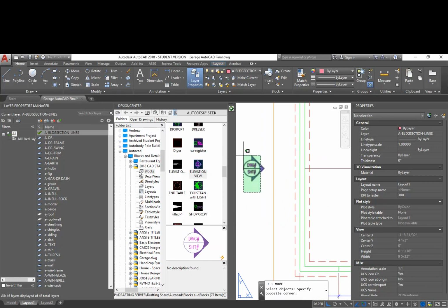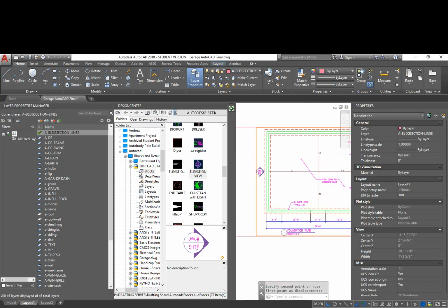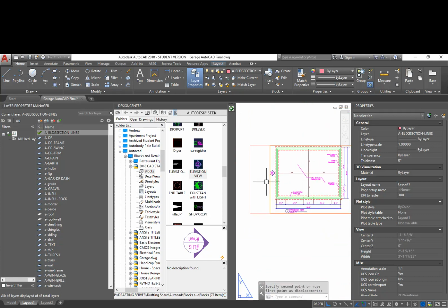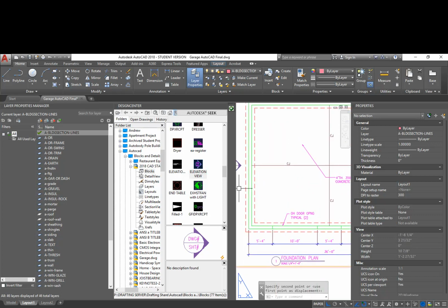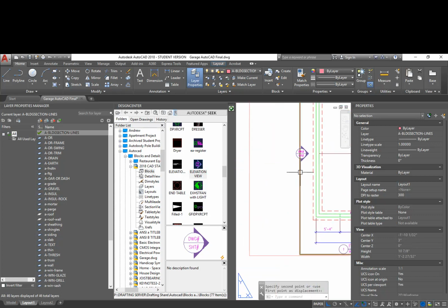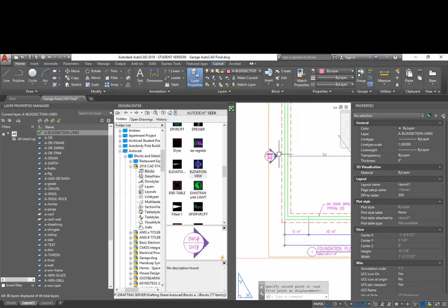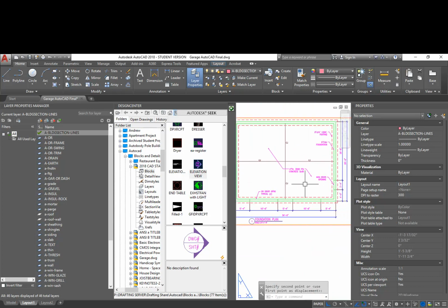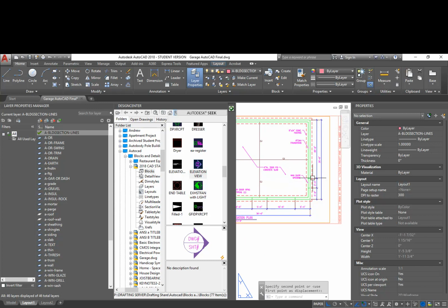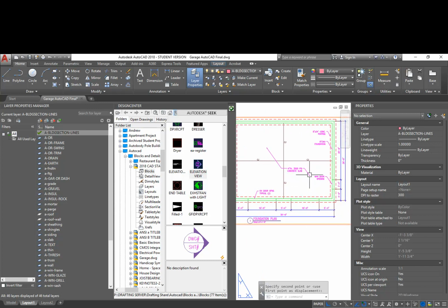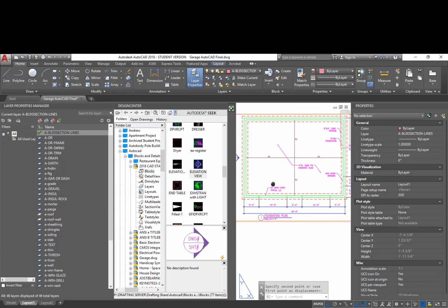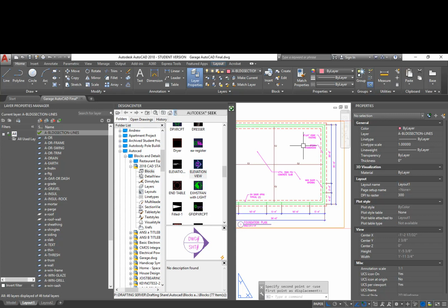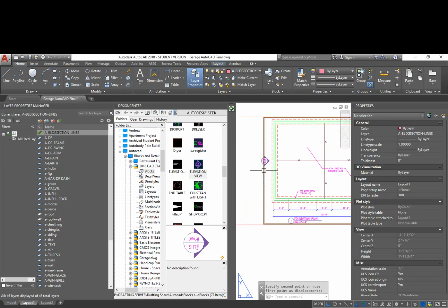and I'm going to move this into place. Have plenty of room here, so I don't have to get so tight with that. I can move this out here. And again, this viewport isn't going to be plotted, so I don't care about placing this over top of that. The only place I'm going to have trouble is fitting it on these sides. Actually, I only have 2 elevations, so I don't need one up here and I don't need one over here.